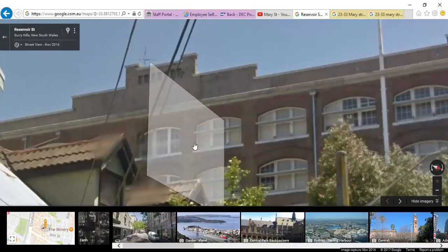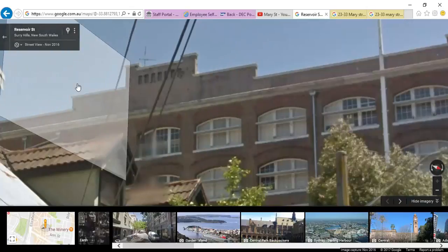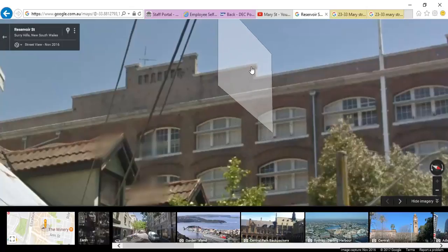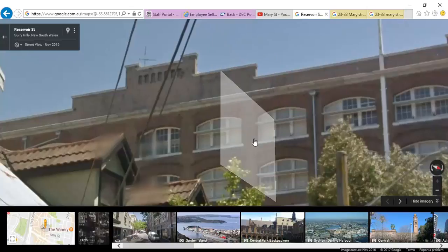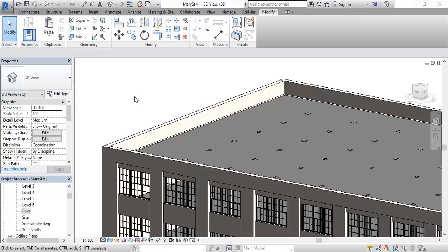So notice that here I've got the 3 window bays, and I can use those to set out the edges of my step parapet as well. The pier here should project up to the line of that parapet. Like a lot of things in design, once you work out the system, you often don't need all the measurements that you might think you need, because you can, again, follow that system to work out your sizes.